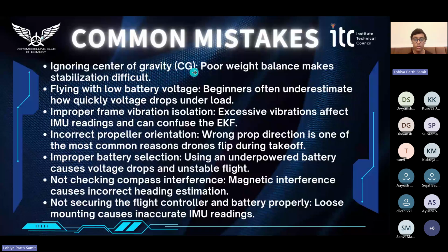Flying with a low battery voltage, this is just something that I'll point out. When flying a drone, it has a maximum flight time of around 5 to 10 minutes. And so beginners often make the mistake of underestimating how quickly this voltage can drop, especially when we have motors, sensors, cameras running all around. The next is improper frame vibration isolation. So this can lead to noise in our sensors, which can then confuse the EKF.